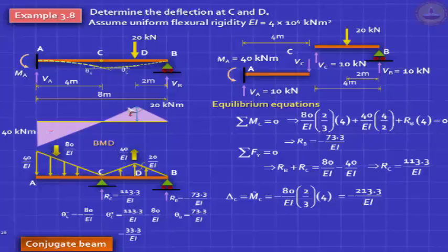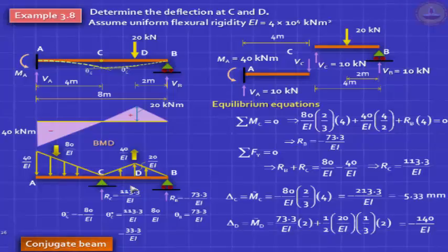If I want the deflection at D, it's the bending moment at D. So I have the support reaction, very easy to find out. You can calculate, draw your free body and calculate your answer. So that's it. You should put a modulus sign and give delta C, delta D. No method can be faster than this method.